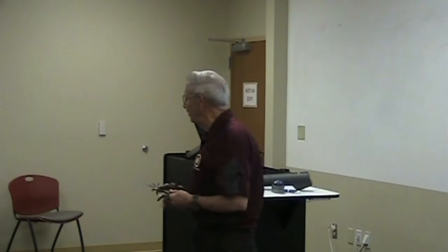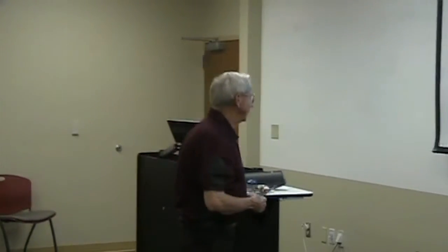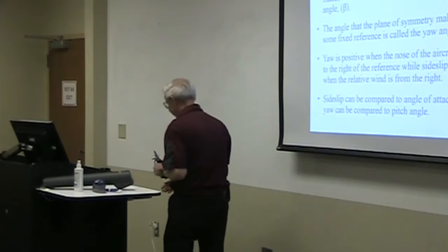And so they used to be amazed that we go through all these big oscillations. One of the airplanes we had a very unstable phugoid motion. I had somebody looking at the angle of attack gauge on that airplane, and of course during this whole oscillation, the angle of attack stayed the same. But the pitch angle was making big changes. They had a hard time with that.